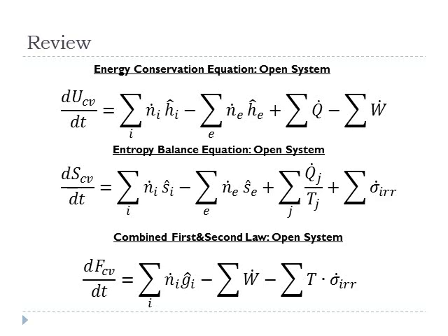And this time, any thermal energy, if it comes in at some temperature T sub J, then the entropy associated coming into the system would be Q dot J over T sub J. And then, of course, what we have is any internal irreversibilities occurring inside the system. That's the last term there.